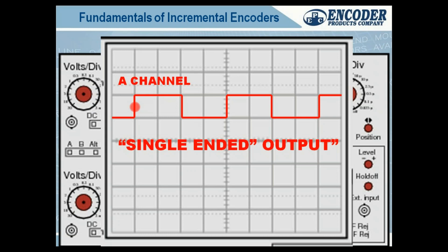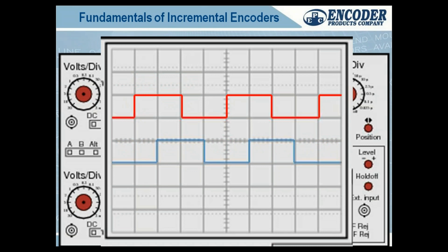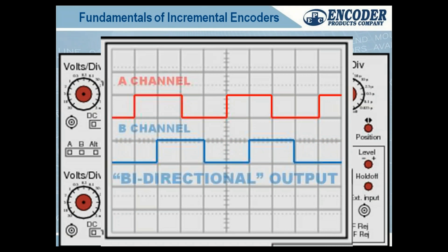But what if you have an application, a CNC machine, for example, where you have a back and forth? Maybe it's a cut-to-length, but you need to be able to reverse the material to prevent scrap. You need to add a B channel. So in the 1970s, let me get out my pointer here. There we go. The sensor was adjusted on the disk and added an offset sensor.